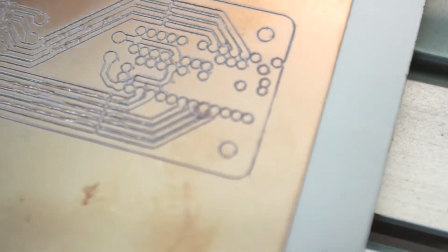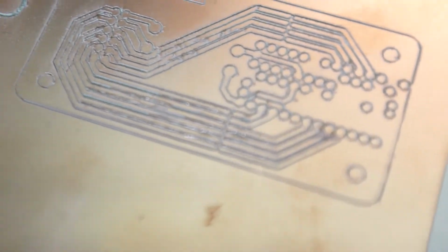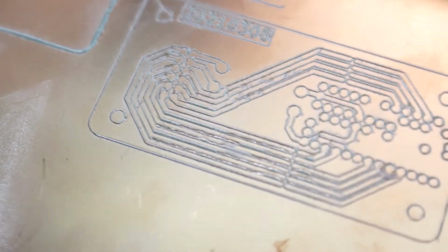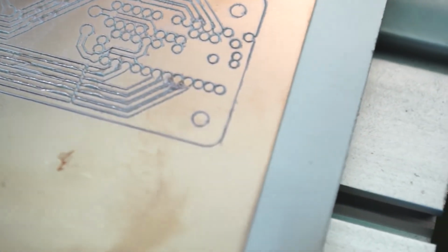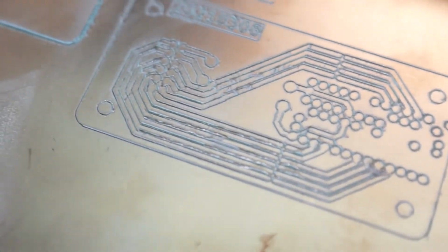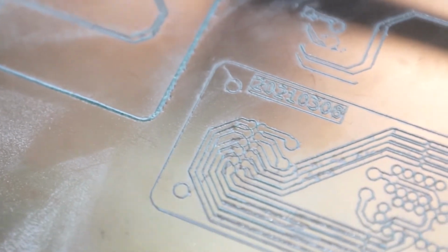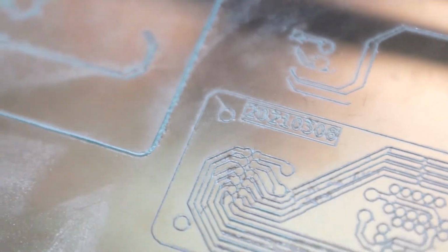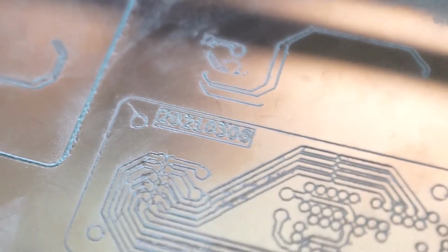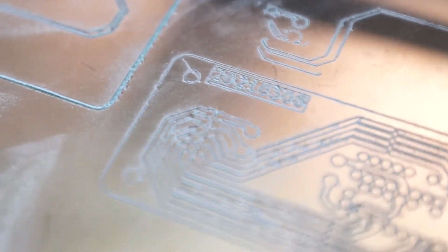You just have to make them a little bit thicker. And by putting them roughly as close together as your tool width, it means that you only need one pass to cut out the space between the traces. So this milled pretty well. You can see that the features on the date are actually not visible very well.